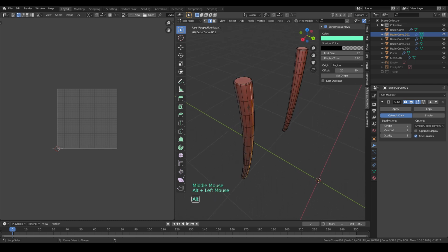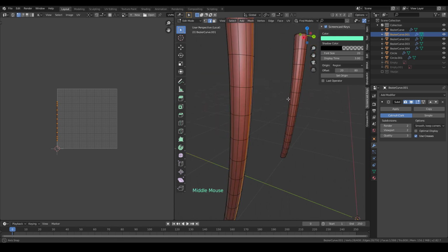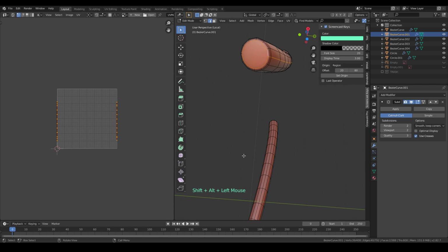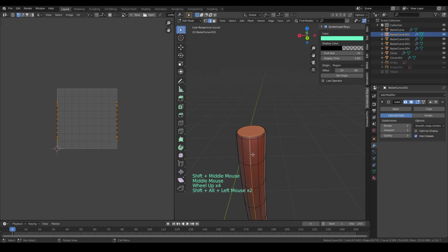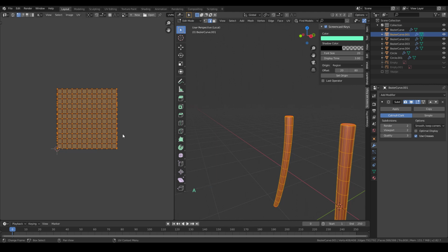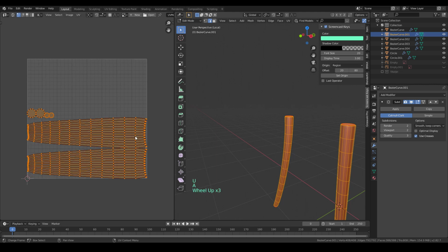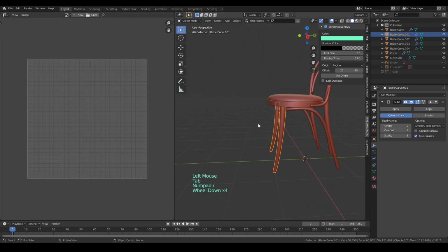So first I'm gonna select this one by Alt and select. So we select on the loop here, and then Alt and Shift to select the upper, and then the bottom one. Okay, I'll do the same for this one. Then right click and mark seam. Okay, then we hit U here. Okay, maybe rotate it by 90 degrees. Look like a pain, and what a strain.